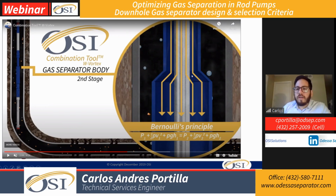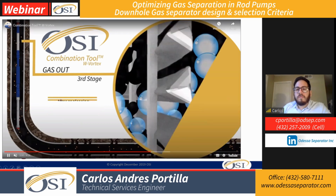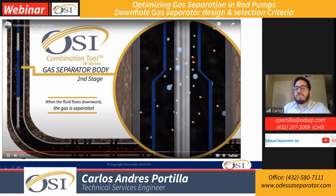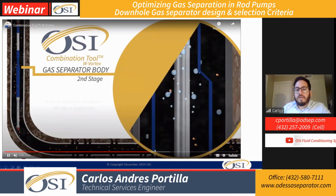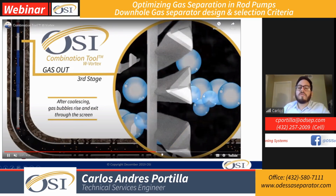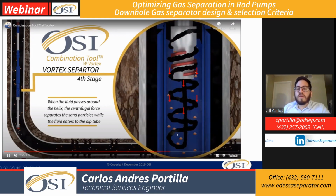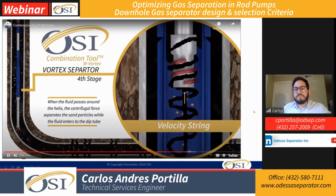In this section, what is going to help us is to reduce the velocity. The gas bubbles will decrease in velocity here, and they will start rising again, like here. There you go. See how the gas bubbles start rising up, and then we'll be purging those gas bubbles through the tubing screen or the intake section. Here we have our vortex, which I mentioned before. It's going to help us break the gas locks and separate sand.